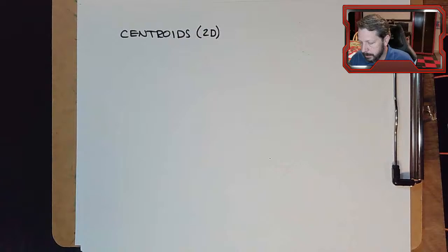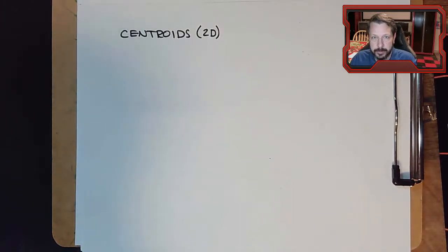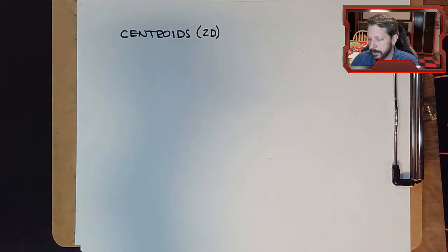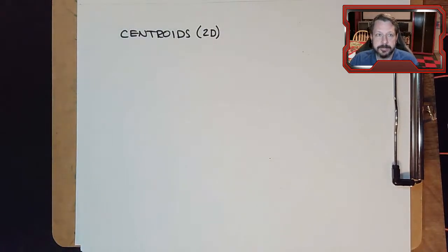We're moving into a topic now that has to do with beams versus where we were with trusses having members. It sounds like they're just different words, beams and members, but they're the same thing. We're trying to make the distinction that they are the same. They might literally be the same piece of metal, but we're applying the forces to them differently. We're going to use beams to mean pieces of a structure that might flex or bend, and we're going to use member for pieces of a structure that only stretch or compress. They don't bend. And so they have different loads on them.